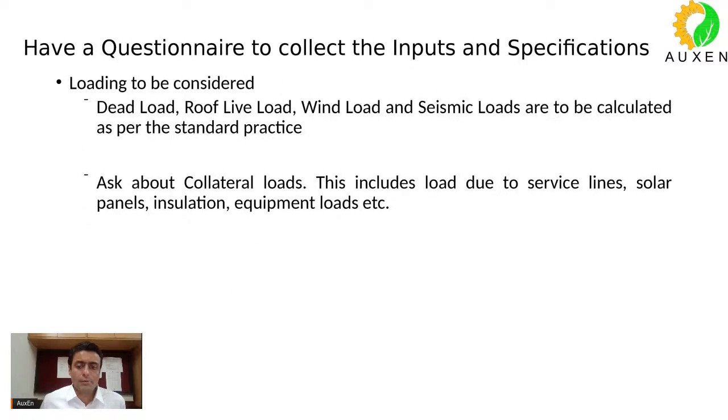Very important. What loads to consider? Of course, dead loads, roof live loads, wind, seismic, that anyway we consider, but ask about the collateral loads. What is the meaning of collateral loads? So in the pre-engineered terminology, collateral loads means loads other than what I've listed above. They are sort of superimposed dead loads.